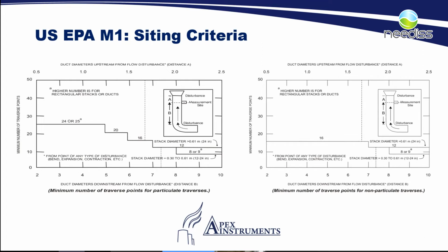Maybe you are measuring down here at the bend or something that is creating problems, and they want to know what is happening with that flow. You are technically not meeting the method. However, in that situation, you are performing more of a research test rather than a test that is going to be used for reporting values to the government. So in that situation, the equipment will work just fine. Just keep in mind you're making a change to the method in terms of the location.